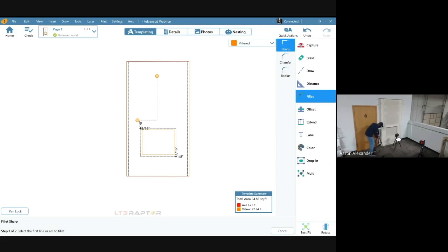So I kind of want to get it pretty close there to the edge. Because again, if you heard me before, you have heard me say, I do not like to move points through space more than 6 inches away from my plane. I don't want to shoot points more than 6 inches away from my plane. So I'm not going to create my plane more than 6 inches away from the surface that I'm trying to capture here. Okay. So I'm going to line up a front laser, square it up to the front edge. And now I have this laser here, which is my plane representing this miter return. So we can take the laser now, and I can set up out here.